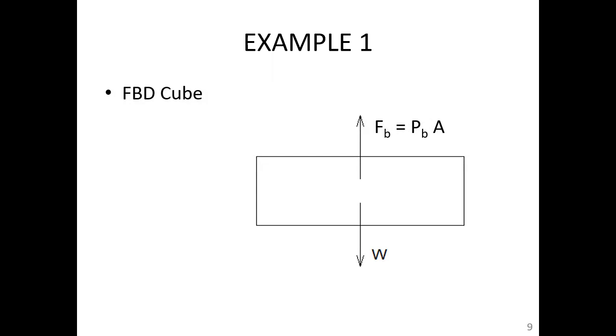In the horizontal direction, yes, we have a pressure distribution on each side, but as I discussed last time, that is no different than looking at the forces on a plane submerged surface and looking at the shadow. So the force on one end is going to be equated by the force in the opposite direction on the other end.